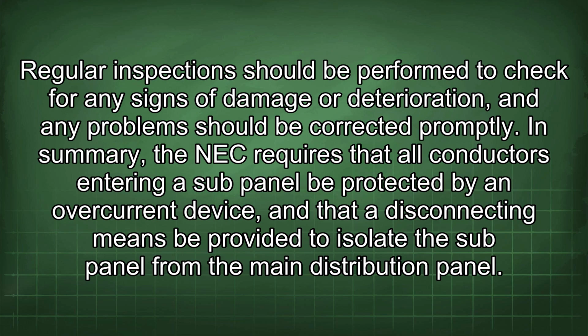In summary, the NEC requires that all conductors entering a subpanel be protected by an overcurrent device, and that a disconnecting means be provided to isolate the subpanel from the main distribution panel.